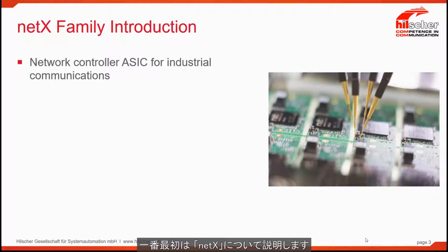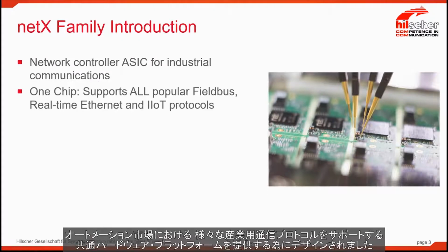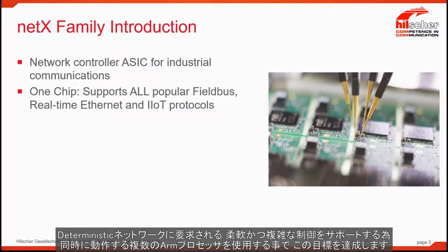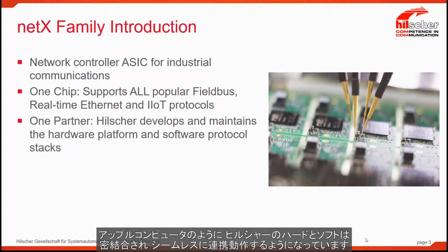First of all, what do we mean by netX? netX refers to an integrated semiconductor platform developed by Hilscher Communications about 15 years ago. It was designed to provide a common hardware platform that would support any industrial protocol within the automation context. It achieves this goal by using many ARM processors operating concurrently to support the flexibility and complexity required by any arbitrary deterministic network. Like Apple Computer, Hilscher's hardware and software are tightly coupled and work seamlessly together.